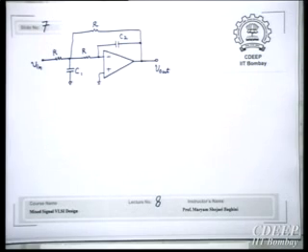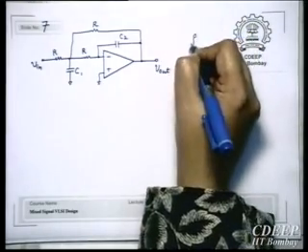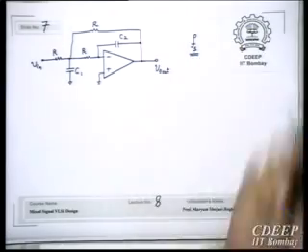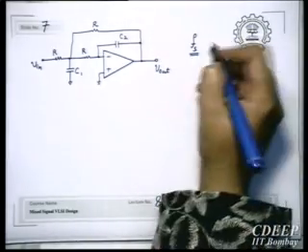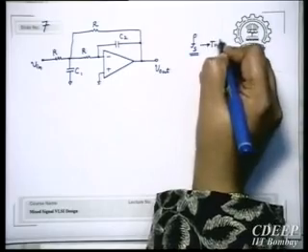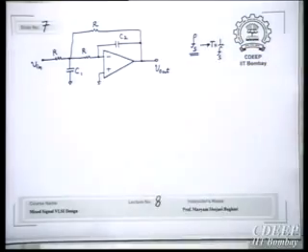Now suppose you want to change this to a switched-capacitor circuit, right? You have designed everything and the values of R and C1 and C2 are correct. So what you need to do is just replace, right? Because you know the sampling frequency is always known already, therefore you need T. You don't touch the capacitors, they are as they are. You just replace the resistors, right?